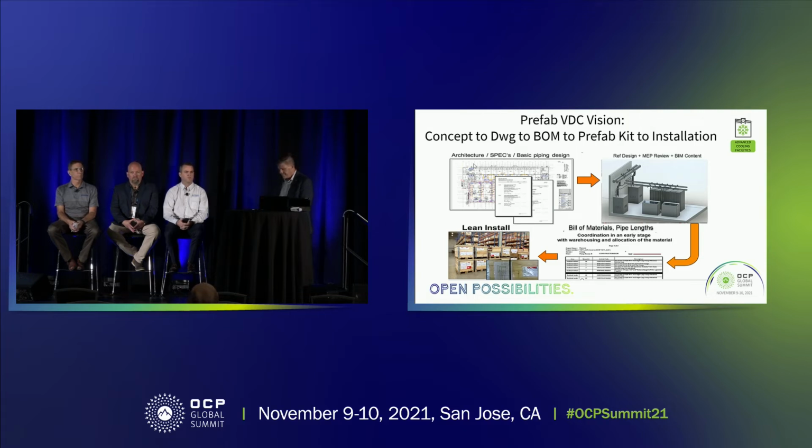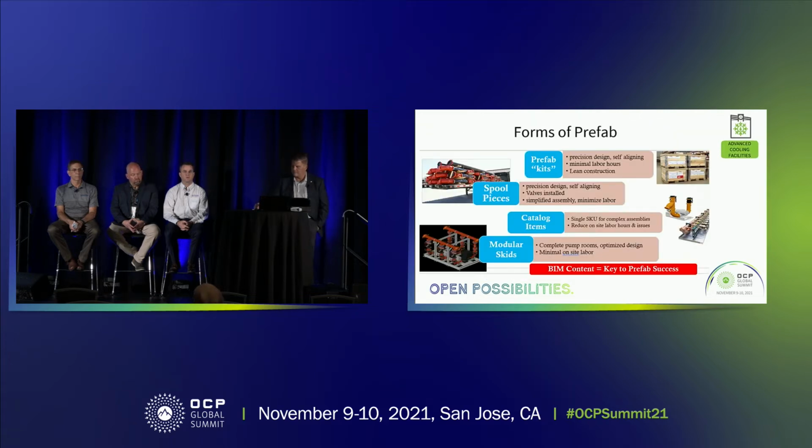So one of the things that prefab gives you is the opportunity to be doing a lot of parallel construction that's not necessarily all happening on the same site. If you can modularize your cooling distribution or your power distribution, skid package it, put it on the back of lowboy 18-wheelers and have it show up pre-manufactured, ready to slide in the building as the building's getting dried in, then you can help to overcome quite a bit of the supply chain issues that we're having right now.